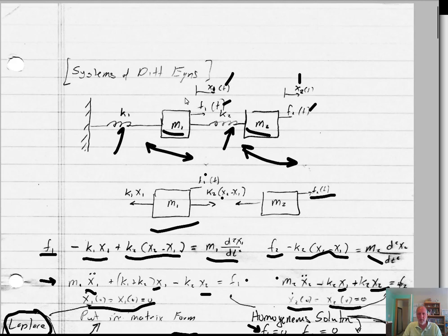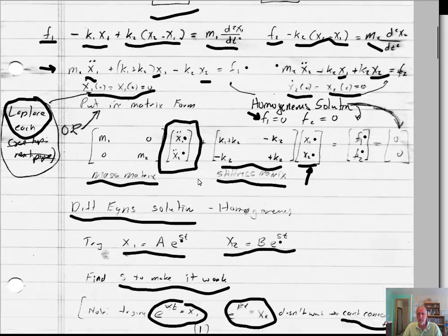And the 2 masses relative to each other can go forward toward each other and away from each other. And so we get the 2 different frequencies of motion. Or you can think about it as there's a frequency of m1 and m2, but that's not true, because each of the solutions, x1 and x2, have both frequencies involved. So you can have both masses moving back and forth together, or you can have the masses moving toward and away from each other. And that's where you get the 2 different modes.